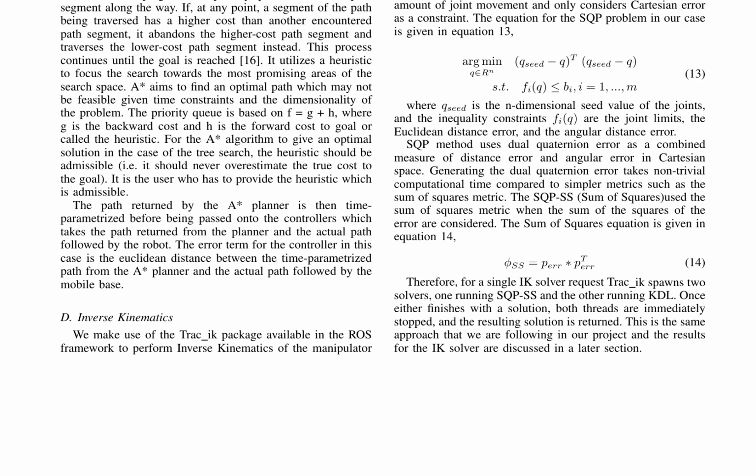In addition to the trajectory planning and control, the authors implemented a state machine in C++ as a ROS node named fetch_trajnode. This node automates the entire pick-and-place task by executing tasks sequentially according to the predefined flowchart. The state machine transitions between states upon receiving transition requests in the form of ROS messages after completing previous states.